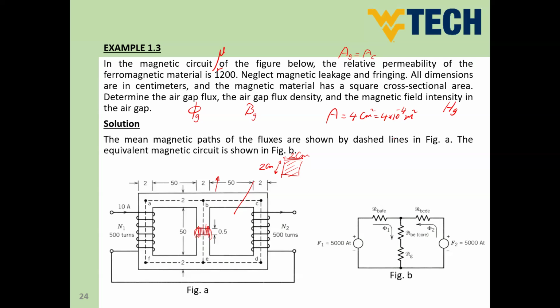Nice. First step is, let's firstly delete the lines that I have here. Sorry. First step is we need to convert our magnetic circuit into equivalent electrical circuit. As you can see, guys, we have here two sources of flux. The first one in the left arm has a certain coil of 500 turns and the current is 10 ampere. And we have another coil here of another 500 turns. And if you have a look, you will find that the current of the first coil is moving and connected to the second coil. So firstly, we need to observe the current and the flux direction.